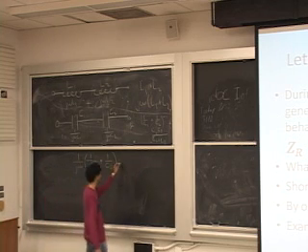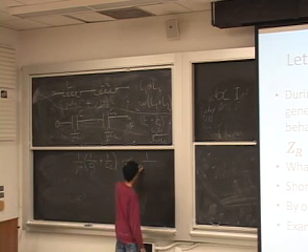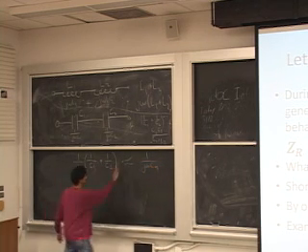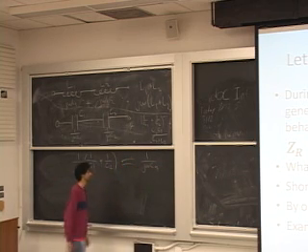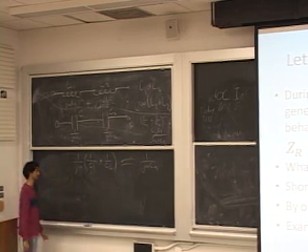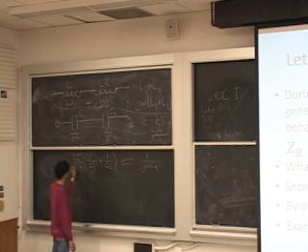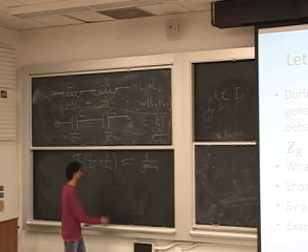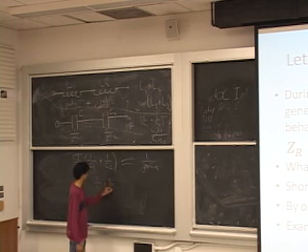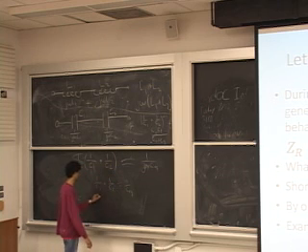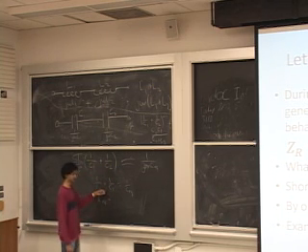Let's say we want to get to 1 over j omega C equivalent. What can we do to bring out this relation? We can just cancel out these 1 over j omegas. We have our original series relationship, that 1 over C1 plus 1 over C2 equals 1 over C equivalent. Or we just say C equivalent equals this business inverted.